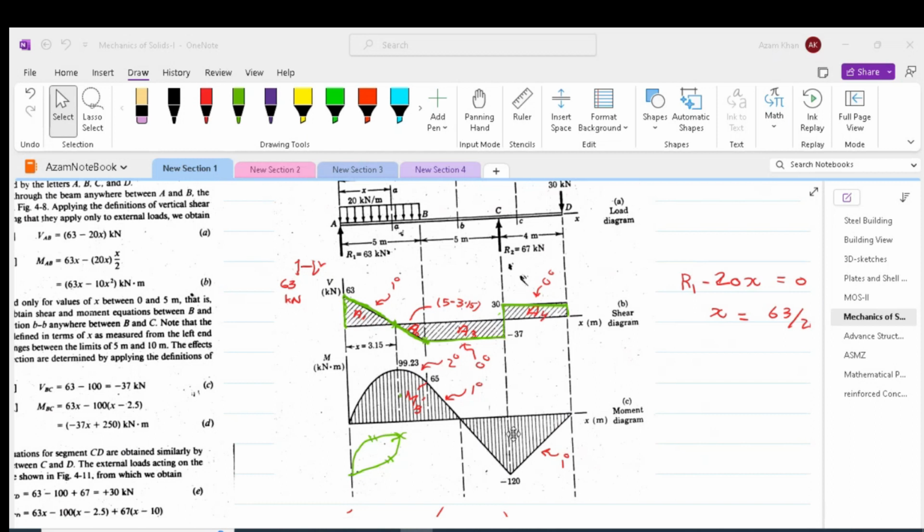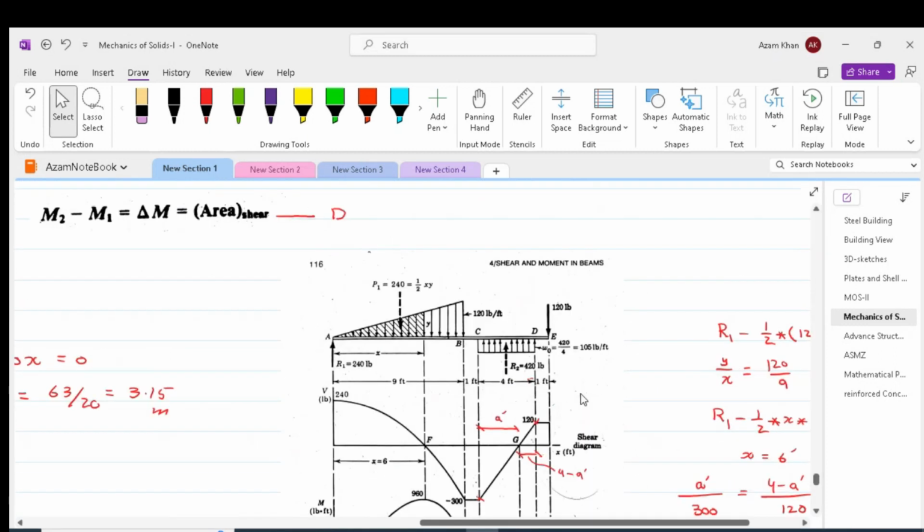From the bending moment diagram, we can say that if our support has got the spans on both sides, then we would have same moment but in opposite direction appearing on both sides in such a way that the summation of that moment will be equal to 0. Now let us quickly run through this another example.